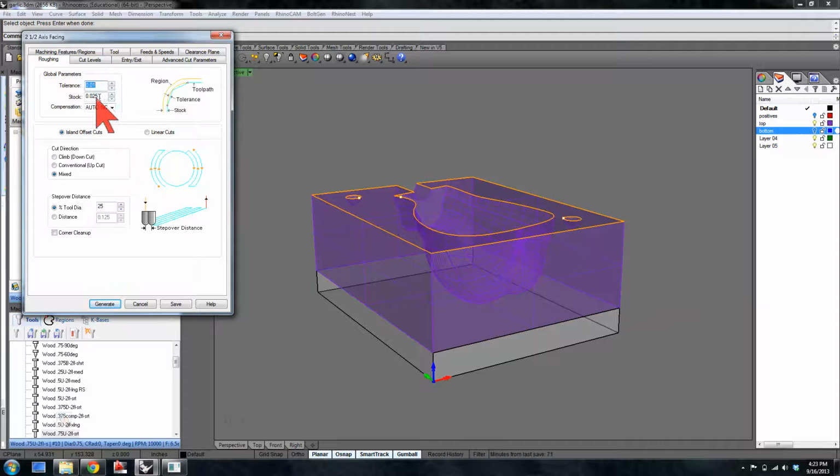The roughing pass, in this case, there's many different passes in a lot of different tool paths. They're not all unique. They're not all the same. Roughing is sort of a typical operation for a facing, but we're actually going to use it for a finish. But you always want to double check the stock number and make sure that it is 0 if you're trying to go directly to your model surface. If you want to leave a little bit of extra material for a finishing pass, then you can add that, to 1/10 of an inch or whatever you want it to be.